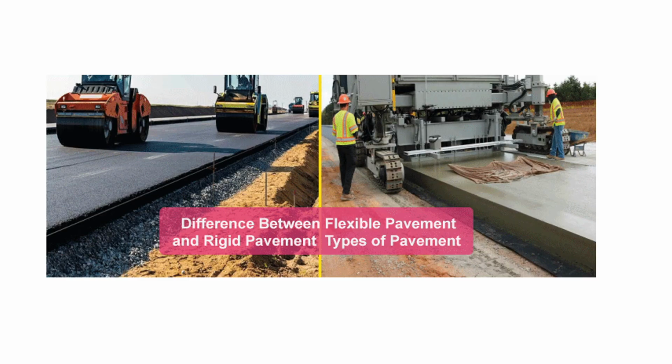What is all this called? It is the layers of the flexible pavement. In that, the subgrade is the bottommost part of the flexible pavement, and after the subgrade there is a GSB, known as granular subbase. It is the second layer from the bottom. Then the next layer will come, wet mix macadam, WMM.